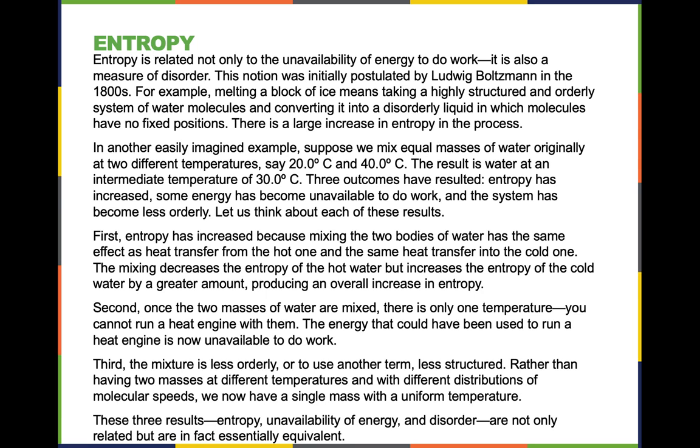First, entropy has increased because mixing the two bodies of water has the same effect as heat transfer from the hot one and the same heat transfer into the cold one. The mixing decreases the entropy of the hot water, but increases the entropy of the cold water by the greater amount, producing an overall increase in entropy.